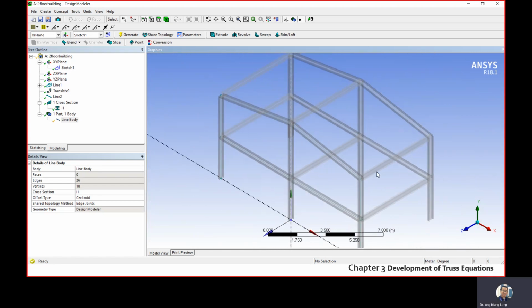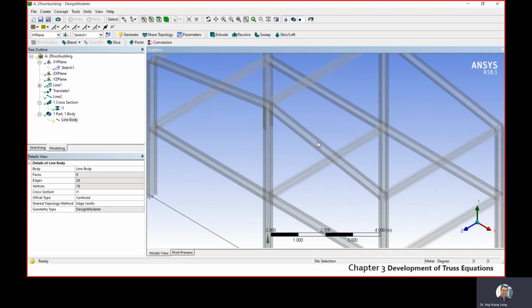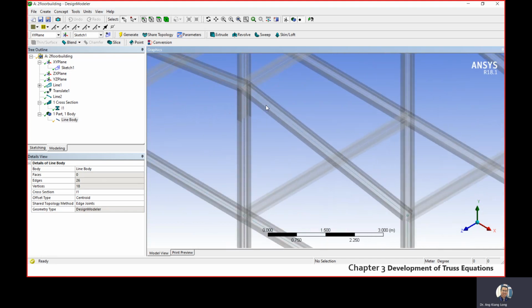However, you see that the alignment of the I-beam here is a little bit off orientation. You are seeing H beam here. So this kind of setting is not strong. We need to rotate the beam here 90 degree clockwise.